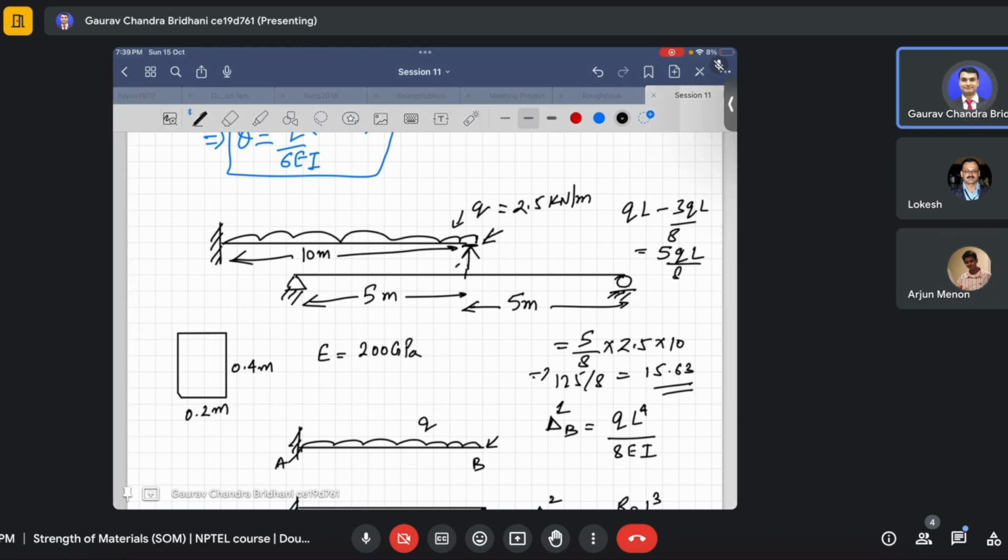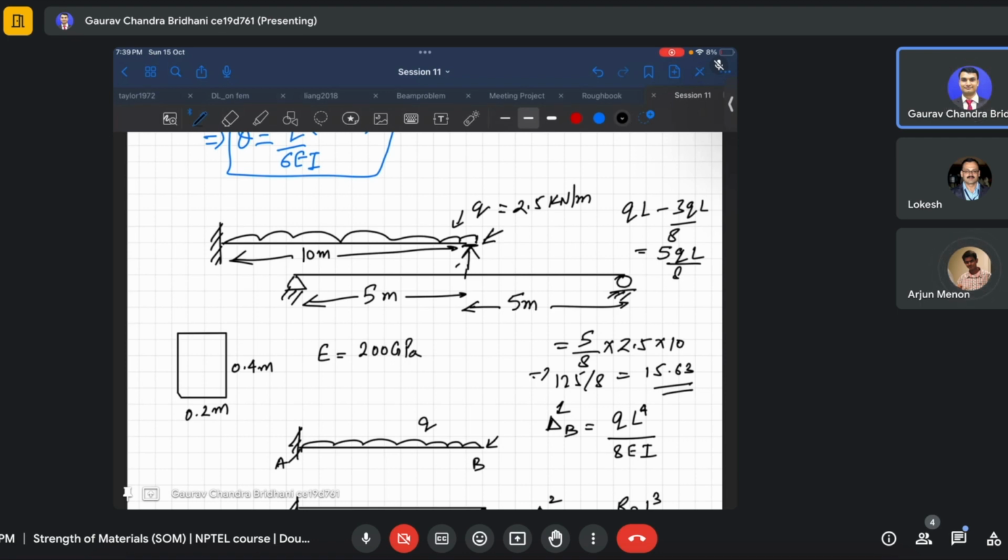And because it changes the geometry. If deflection becomes higher than the allowable, it will change the geometry. You understand my point? In our analysis, we show the beam by a straight line. As you can see, all we have shown is a straight line. So what happens if the deflection criteria is not met? It will not be a straight line, it will become curved like this. And as soon as it becomes curved, it doesn't serve our purpose. So I think that is the reason.